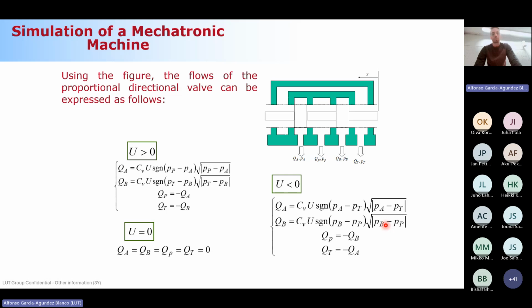Because in many situations, if you do, for example, your simulation project work, you might have recirculations of flow between different ports, and this could lead to a minus sign inside the square root, okay? And have an imaginary number. And of course, a volumetric flow rate is a real number, okay? It cannot be an imaginary number, okay? Is it clear? Perfect. Any questions related to this exercise?